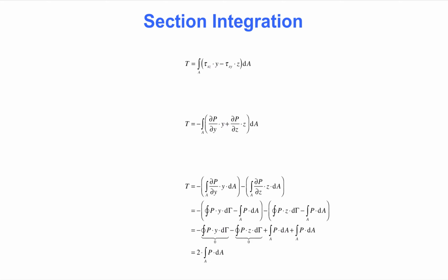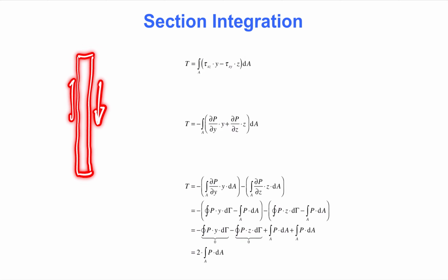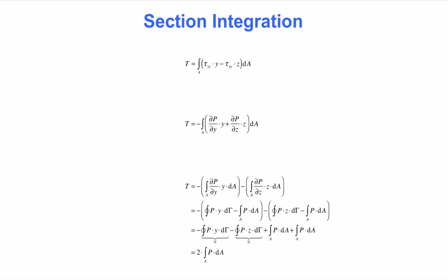In fact, those contributions double the torque because their moment arm is large. In Chapter 10 of their 1969 book on theory of elasticity, Timoshenko and Goodier acknowledge that the small shear stresses that are sometimes neglected can have an appreciable effect because their moment arm is substantial. They also suggest further reading by mentioning that the question was cleared up by Lord Kelvin in Kelvin and Tait's Natural Philosophy, Volume 2, page 267.